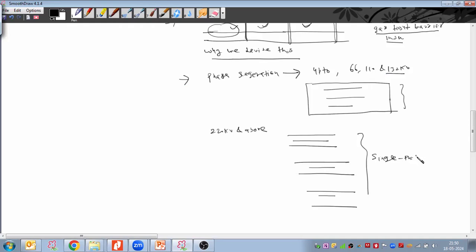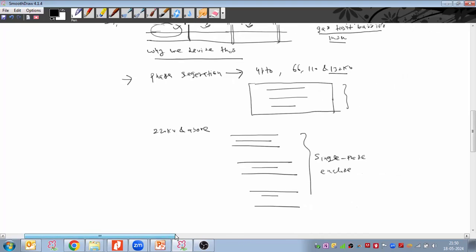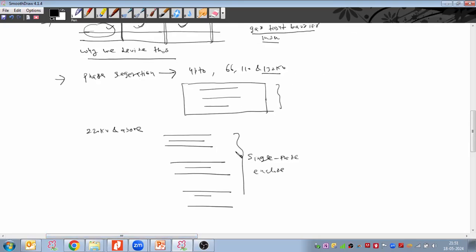Anything, Amol, that you want to add here, or anything as per your opinion? Sir, normally in most cases single phase is used. Three phase is nowadays used mainly for residential, data centers and related projects, for a more compact design and civil related reasons. For 132 kV, if there is no data center and it is a utility project, you would propose a single phase design for this voltage as well. Normally utilities go for single phase only.